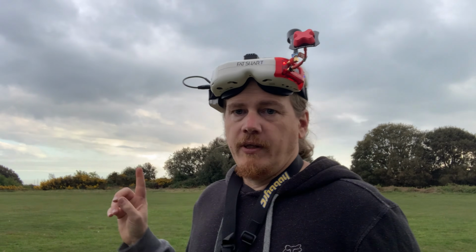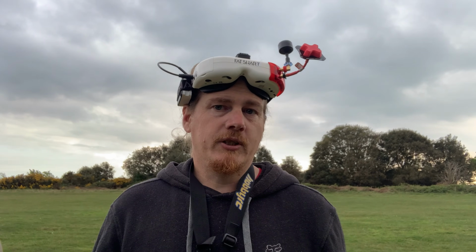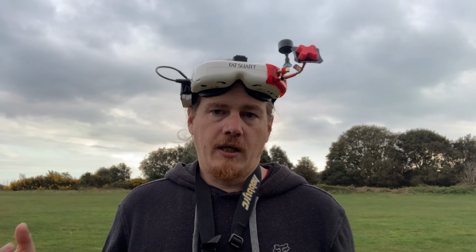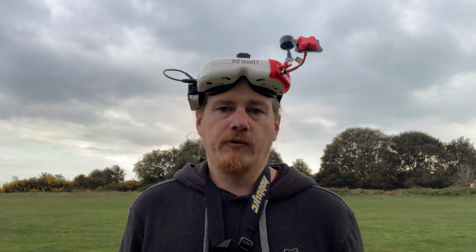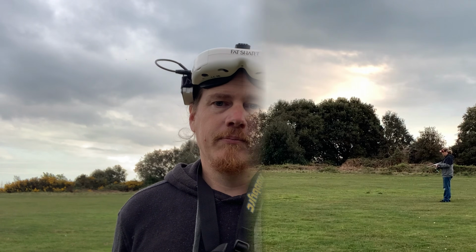Just a little tip. If you walk a couple of meters in the direction you're going to throw the plane, it might help it track better. Obviously, at the moment, it doesn't have a heading. So if you arm it and walk a couple of meters in the direction you're going to throw the plane, it may assist in getting that plane flying straight.